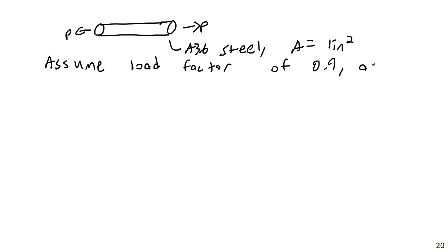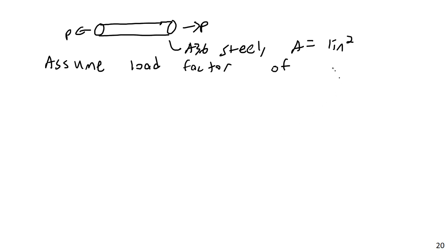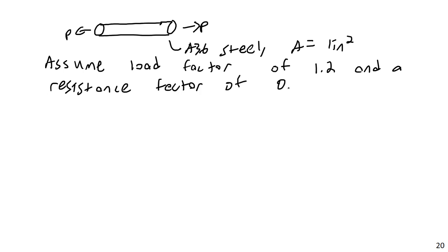And a resistance factor, actually not, sorry, load factor needs to be greater than 1. Did I mention this one is less than 1? Sorry, this resistance factor needs to be less than 1 here. So assume a load factor of, I don't know, 1.2, for example, and a resistance factor of 0.9.